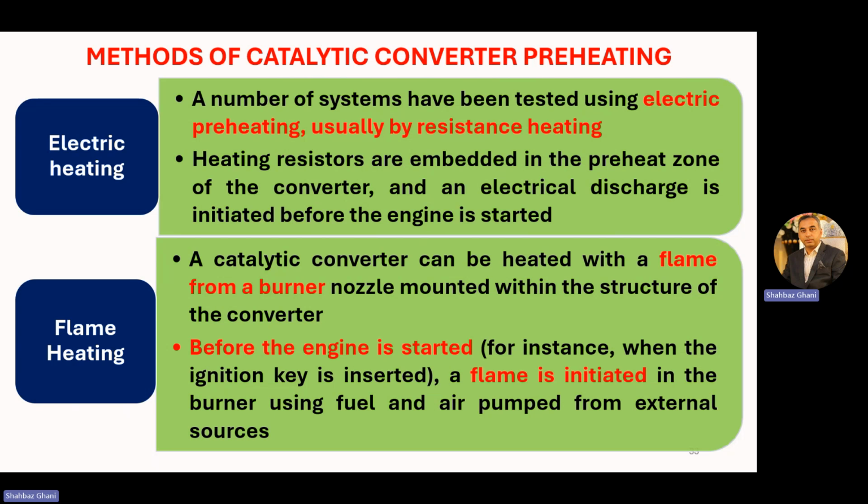Another method for preheating the catalytic converter so that it gives us maximum efficiency is flame heating. A catalytic converter can be heated with a flame from a burner nozzle mounted within the structure of the converter.